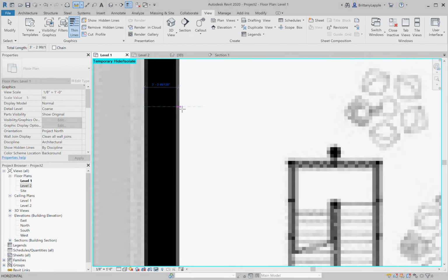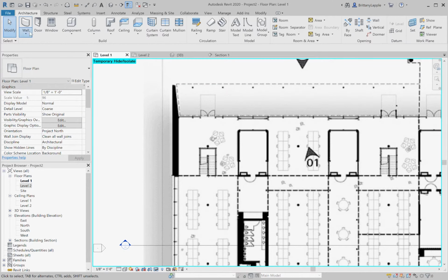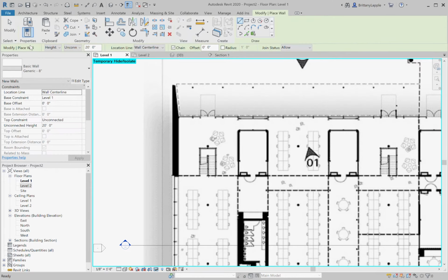You will navigate to the Architecture tab, then select Walls, Architectural. We need to first measure to see what the wall thickness is that we need, and it looks to be roughly 3 feet. So select the generic 12-inch wall option, and then we will edit type. Again, the dialog box that will appear is not visible on my screen.